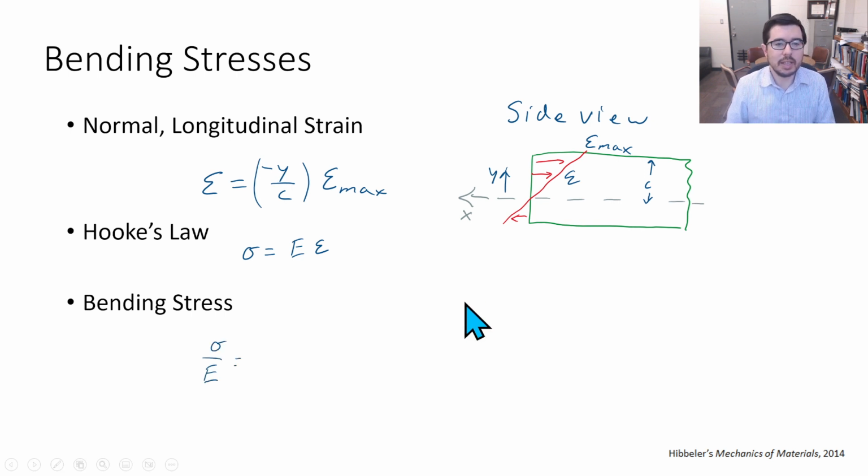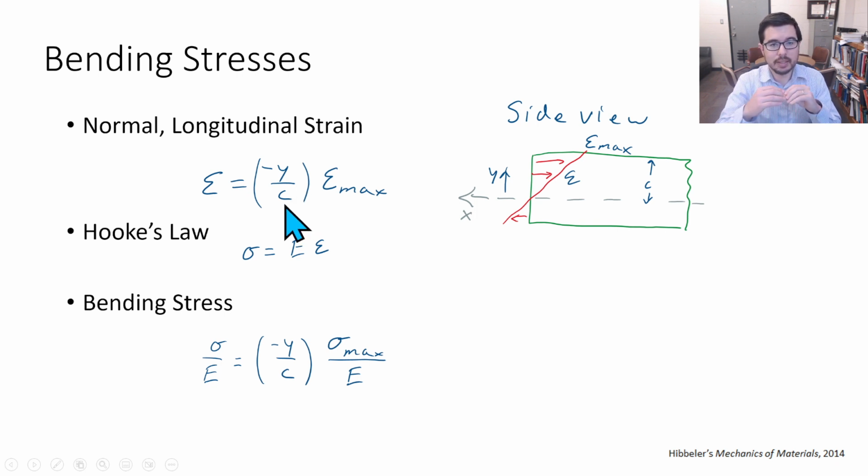Just as we had this expression describing an absolute maximum bending strain at the surfaces, as the distance from the neutral axis approaches often half the height, or the distance to the surface, we have that same ratio, but now applied to a maximum bending stress, say sigma max, and relating it to sigma. As we see here in this diagram,